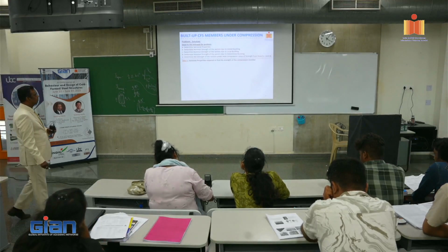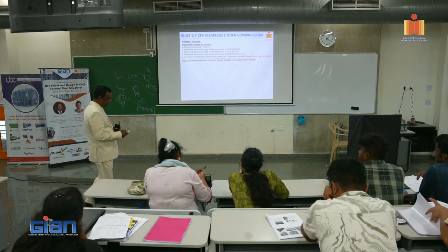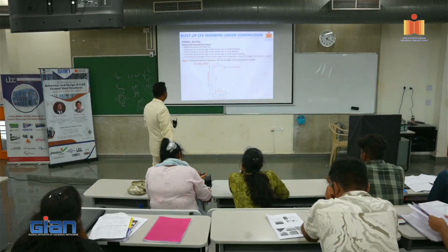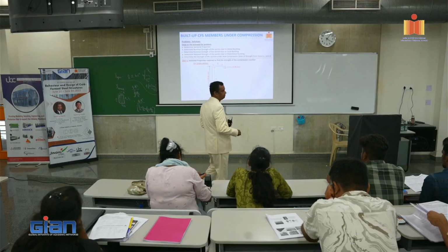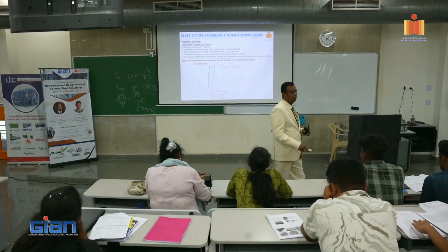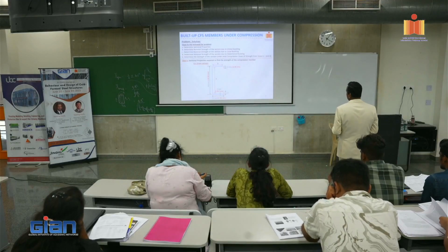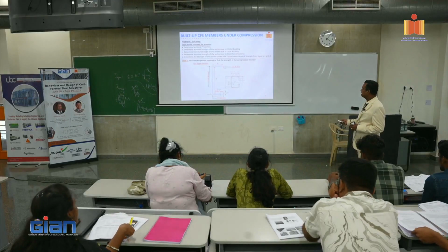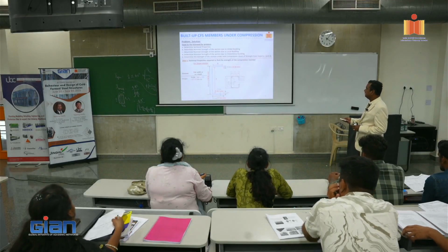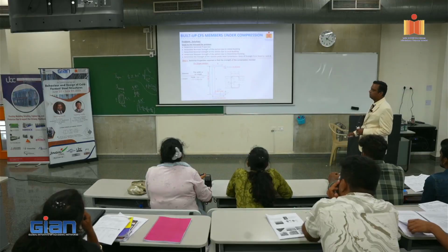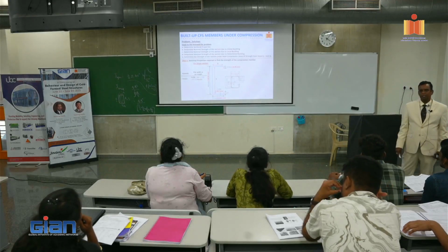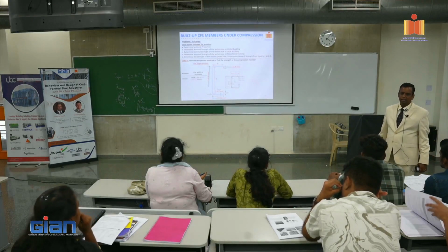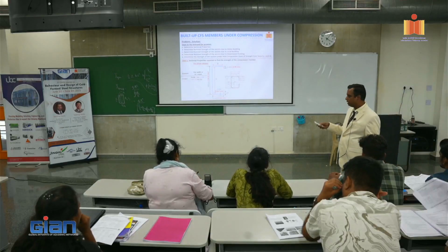So now the section property is required to find the strength of a compression member. For a single section, it is given like this, right? Now what do we do after this one? We have to calculate using these formulas here. So the flat length or width is what we have to find out. The flat width is actually the total width minus the radius, right? The corner radius that you have to find out.